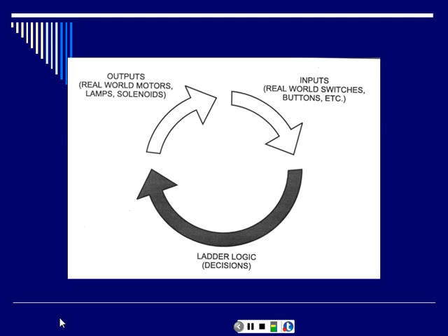We come out of the stop and into the start. That same side of the start has to go down to the control relay, or the relay seal-in contact, right? The other side of the contact comes back up to the other side of that start button. The start button then goes down, and we'll say it goes to the motor. Then the other side of the motor goes to the ground side. Okay? We don't do that anymore.